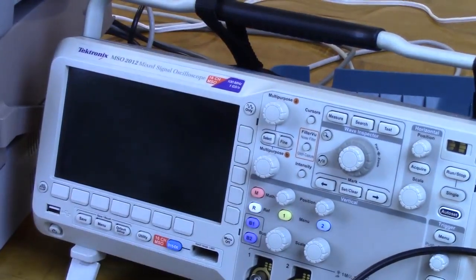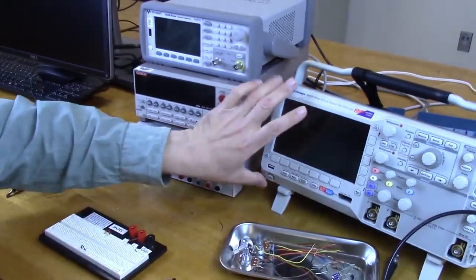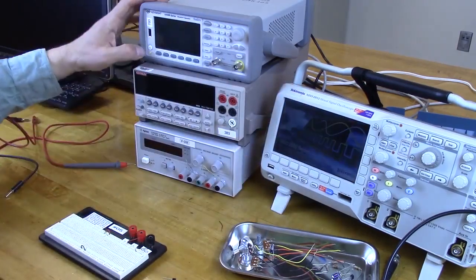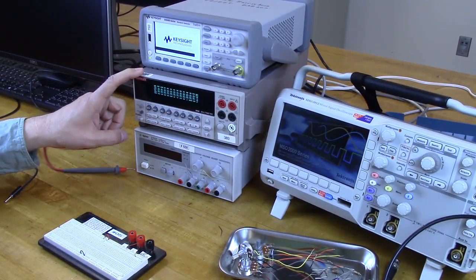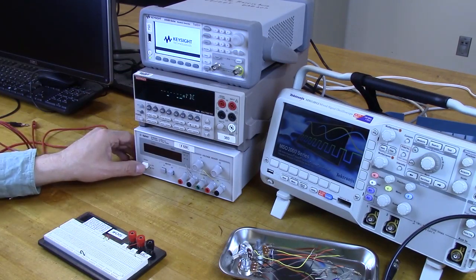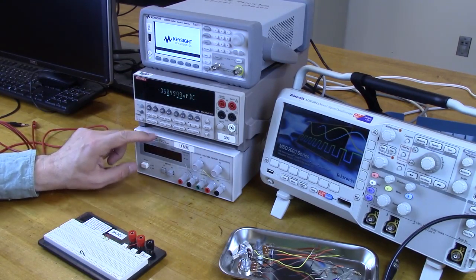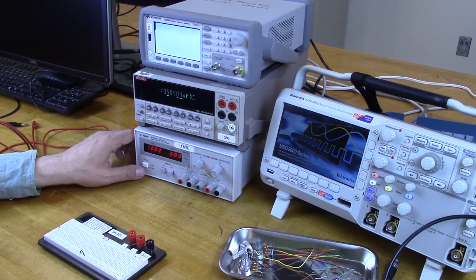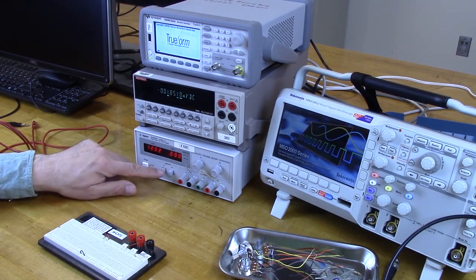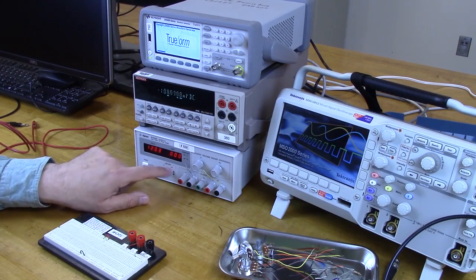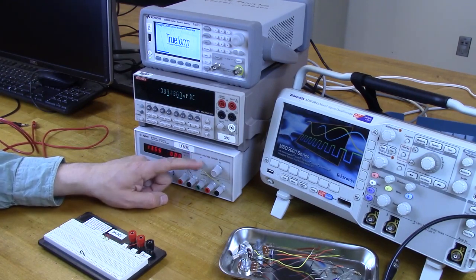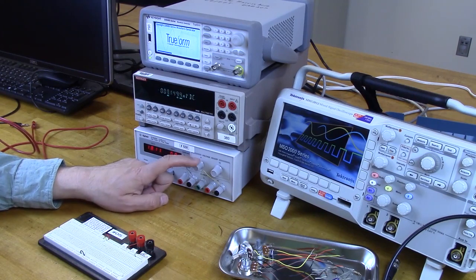Okay, and at this point, I'm just going to turn things on and let them warm up. So let's turn on the scope, signal generator. We're using the Keithley this time as a voltmeter instead of an ammeter, and we're only using half of the DC supply this time. It's set for 12 volts on V1. We're going to be using V1, but we're going to set this for 20 volts. Using a 20 volt supply.